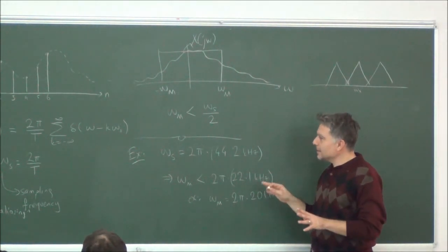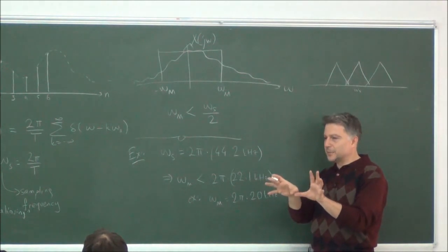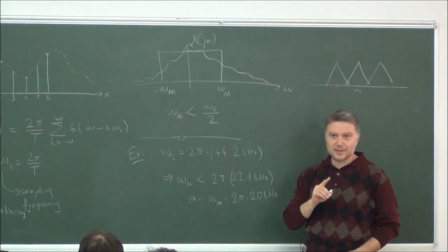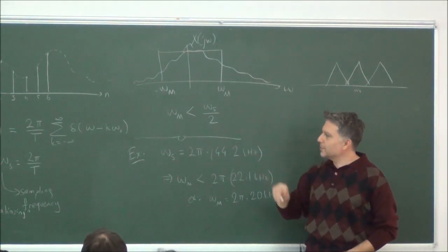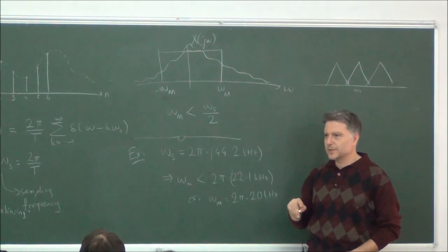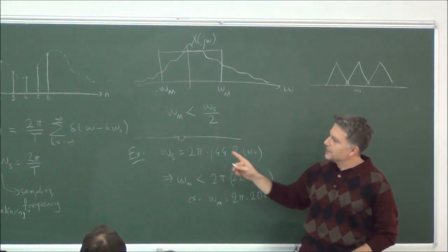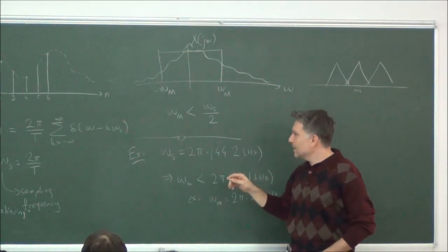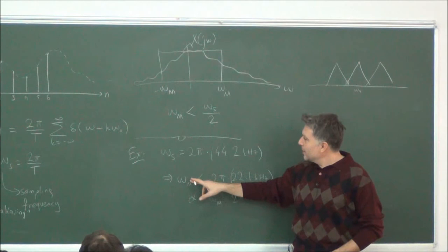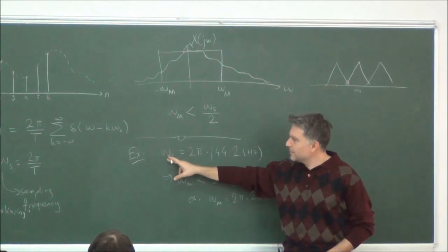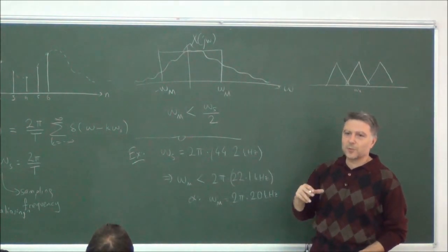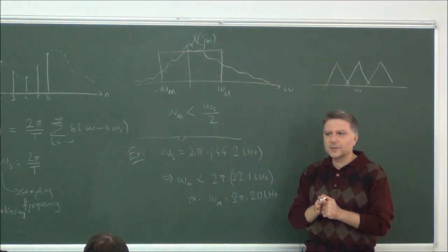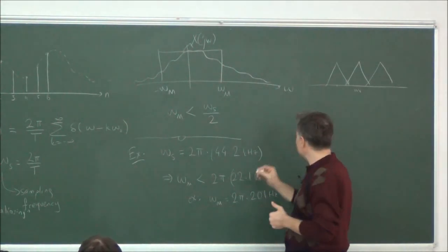But aliasing does not necessarily mean only the maximum frequencies, and usually in exam questions I ask something else. But we're running out of time. We will see more of these examples, and we will also see the low pass filtering and reconstruction process later. Let me give you briefly the idea why in some cases it is possible to have a sampling frequency which is not greater than twice omega m. It is less than twice omega m, but still there is no aliasing. How can it be? It's like a puzzle game.